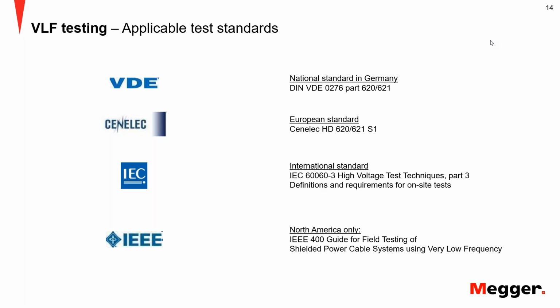Thank you, Marshall. So, Robert, IEEE 400.2 mentions tip up from 1.5 U0 through 0.5 U0. Should we not apply table 400.2 when 3 U0 is used? Okay, you have to be precise here about what you're talking about.